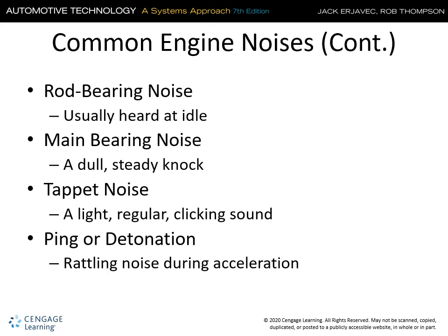Rod bearing noise, rattling at an idle. Main bearing noise is a dull, steady knock. Tappet is a regular clicking sound that's timed to the RPM of the engine. And pinging detonation is a rattling noise during acceleration.